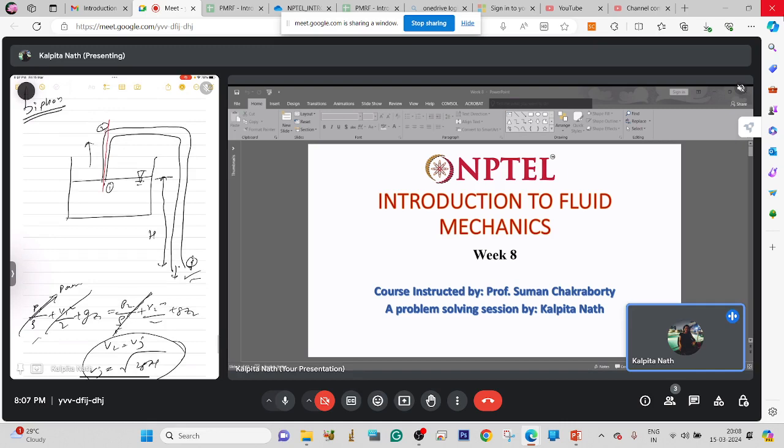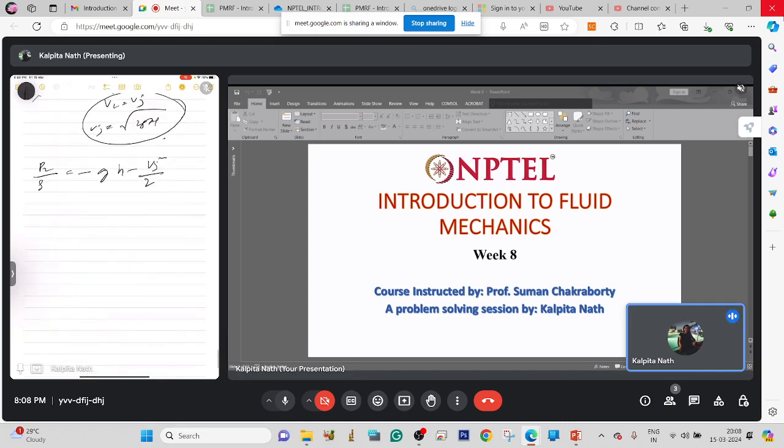If the pressure at point 2 is negative, that means it is below atmospheric pressure, and P2 may fall below the vapor pressure at that local temperature. But there is one concept called cavitation. As the pressure is less than vapor pressure, air bubbles form that get entered into the liquid, and that will shoot along the pipe and will destroy the siphon. In order to avoid that, we have to keep such a height that the pressure does not go below the vapor pressure, right? So that will give us the maximum height.